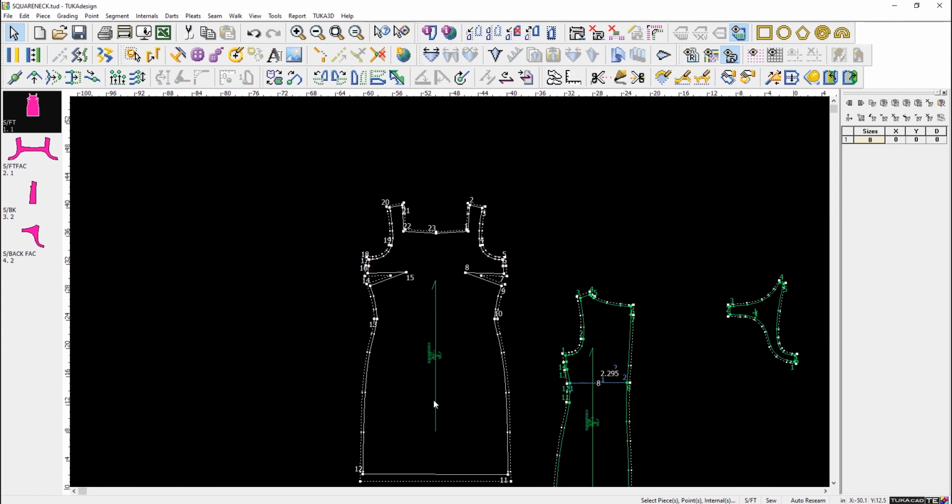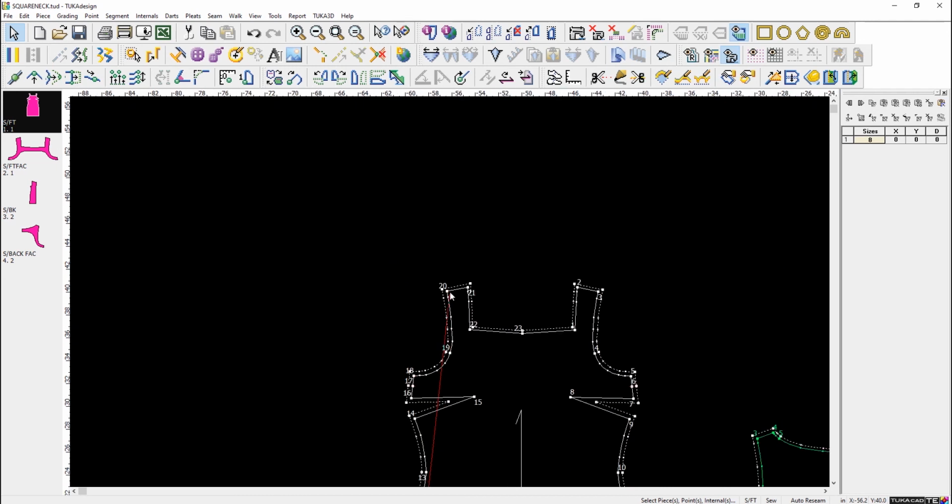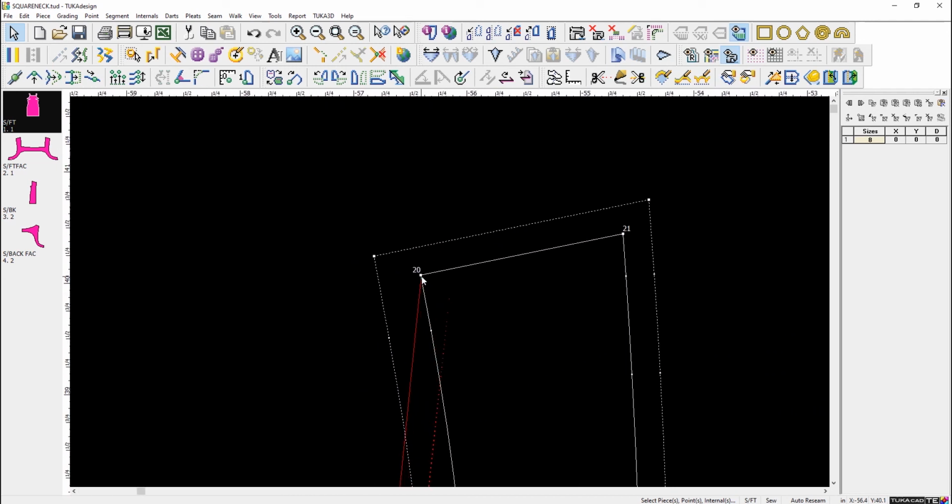I think I forgot to mention how to select the line. Okay. So the way we select the line is you have to click and hold a point, okay? And when you move the mouse, you get this red drag line, okay? And then when you get to the end of the point, see how the point turns red? I don't know, let me zoom in. So once you get near it, it should turn red, and when you release, then you'll select the line, okay? So the reason you have to hold, only with the select tool you have to do this, okay? Because when you click and click, it deselects and selects a new thing. So this is the reason why you have to click and hold.